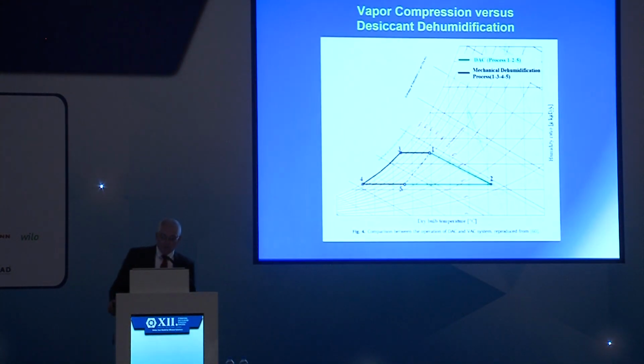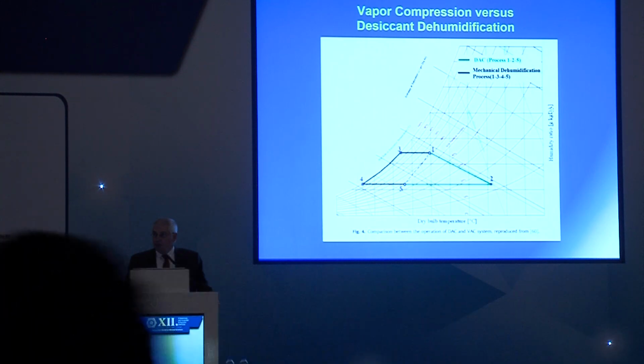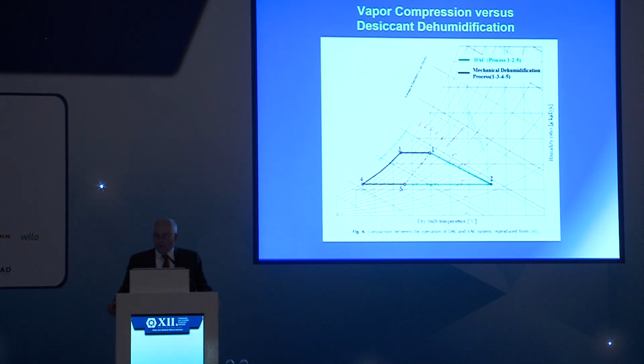So the two systems we'll be comparing are, first, the vapor compression system, which is the 1, 3, 4, 5, where the 4 to 5 reheat step many times is not done. The reheat, unless it's a bypass system, can be very inefficient if we're not actually using waste heat to do that, and it is actually illegal in many places in the United States and throughout the world. Or we can look at the adsorption system, which is the 1, 2, 5, where we have to have some kind of heat sink, and usually that's either outdoor air, evaporatively cooled, or just plainly cooled, or indirectly evaporatively cooled to get to the state 5. So we'll be looking at the green cycle here, at the effects of various parameters on that cycle, and at some of the new developments.